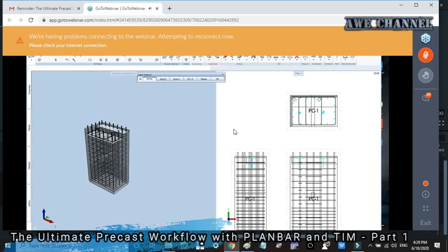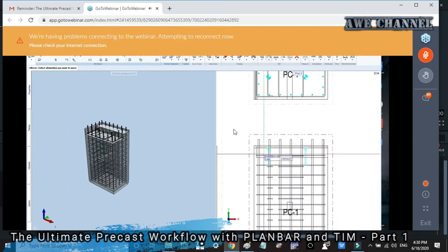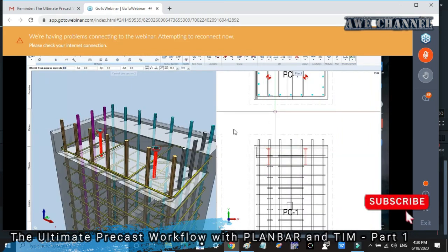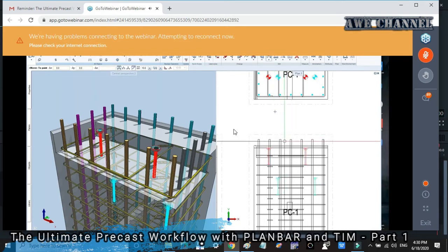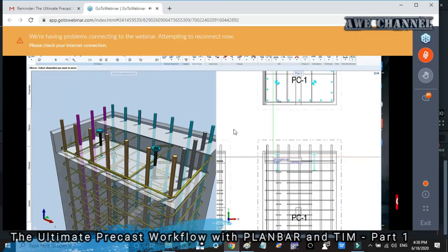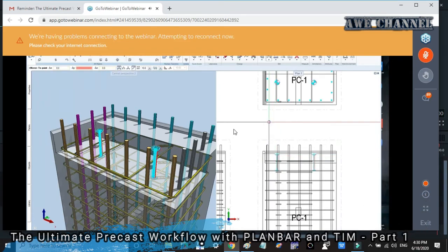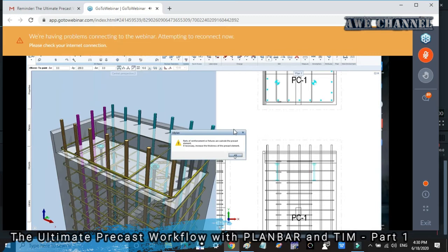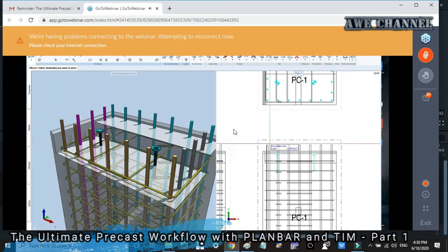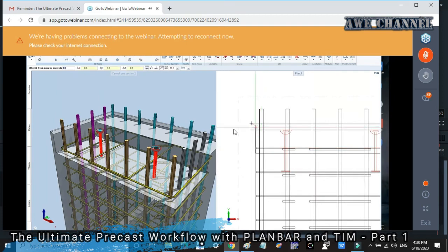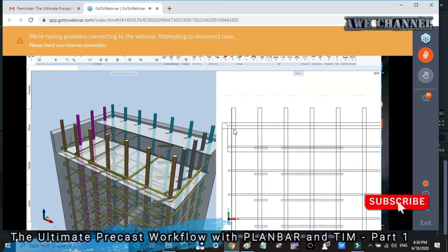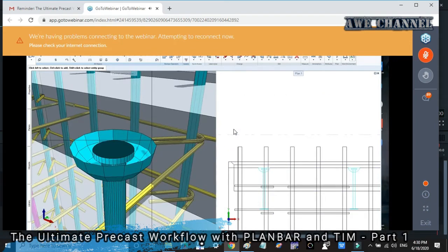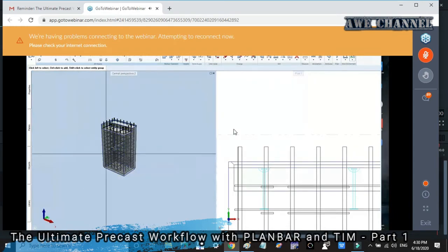Okay, and then we can also adjust it from the top to maybe about 200 on the z-axis. So from here, y negative 200. Make it more lower, so maybe just say from here to here. It's actually there anyway. So that's how you're going to create your precast elements.